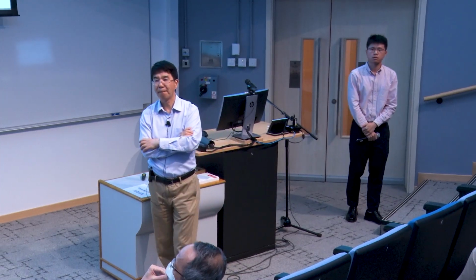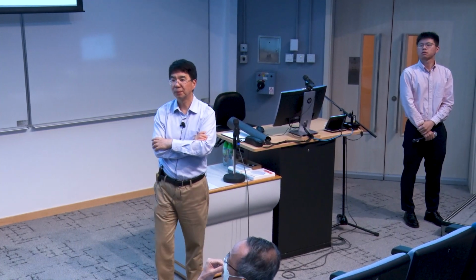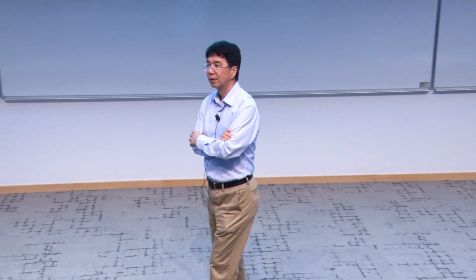Thanks for your talk. My question is, I noticed that in the cross-die cases, you insert registers to address the timing issue. But how do you determine how many registers to insert to solve this problem? Because I noticed that in some academic research, they insert the registers aggressively, but it will lead to area increasing. So how to determine the number of registers to insert?